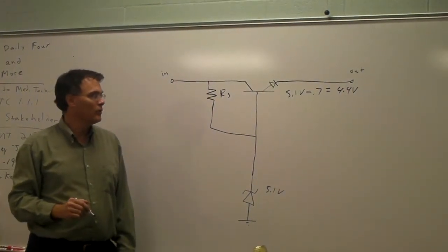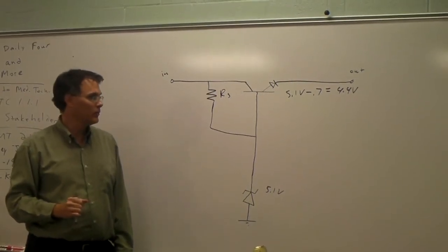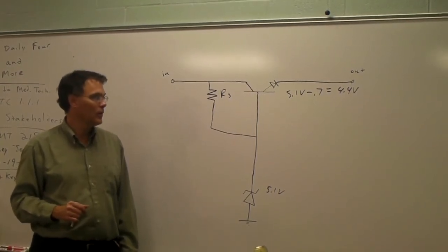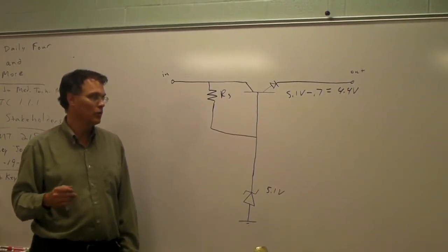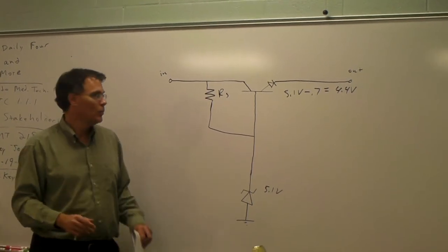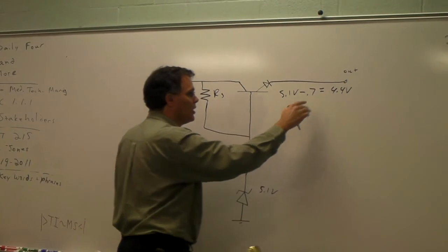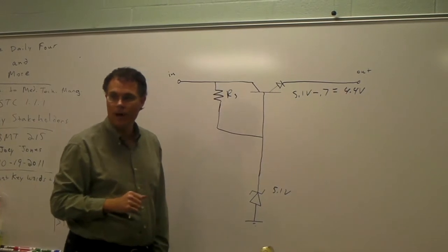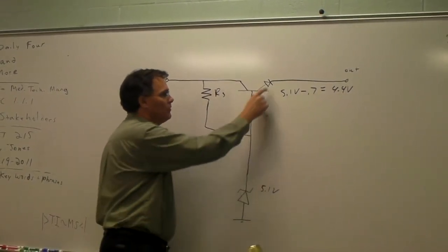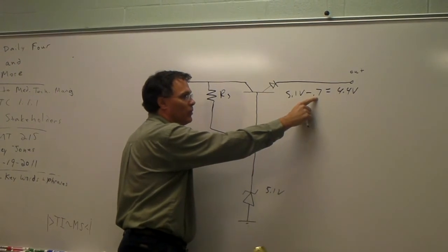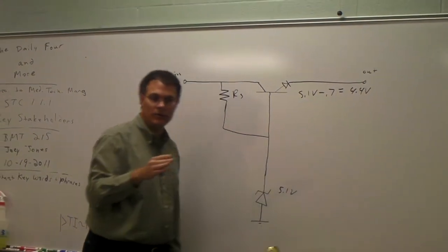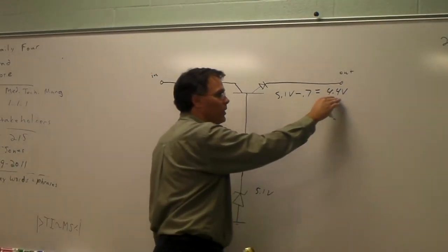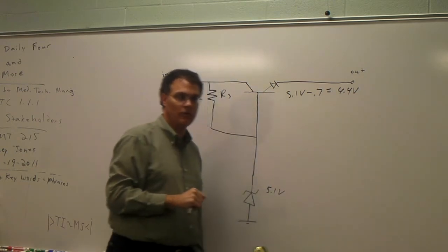That output voltage is the voltage being regulated by this configuration. Now, even though this configuration is simplistic, it lacks good regulation properties. One reason is that as the load current varies on the output side, that current will pass through the bipolar junction transistor and affect the voltage drop here. So this 0.7 volt drop will vary several tenths of a volt depending on the load current, so the output voltage will fluctuate slightly above and below the 4.4 volt rating.